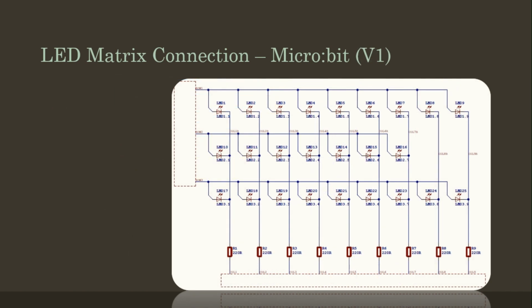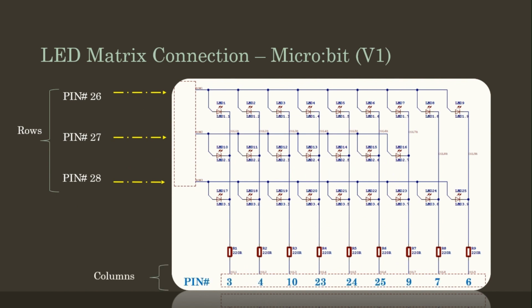In this video, I am actually using an older Microbit board, having version 1.5. This board has different connections for the LEDs as shown here. Therefore, if you are using a V2 version, you will need to change the pin numbers accordingly. Also, please note that the positions of the LEDs on the version 1 Microbit boards are different compared to the same for version 2 boards.